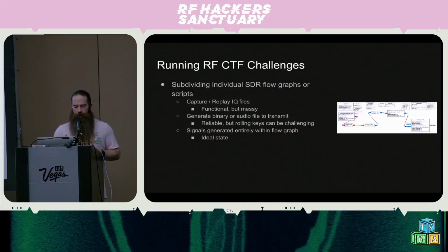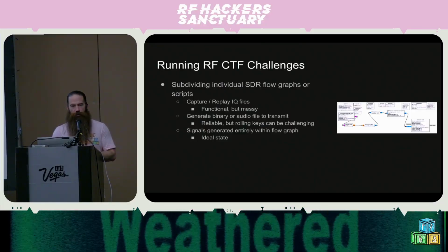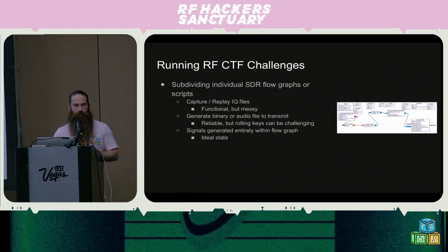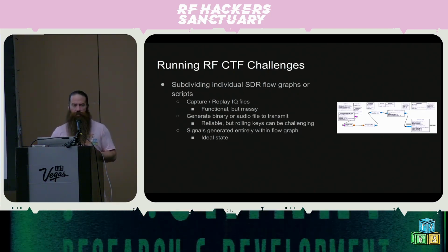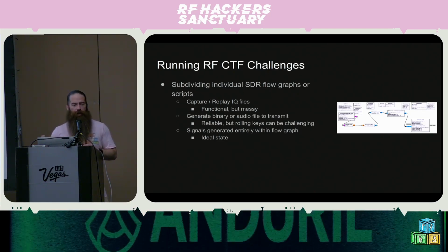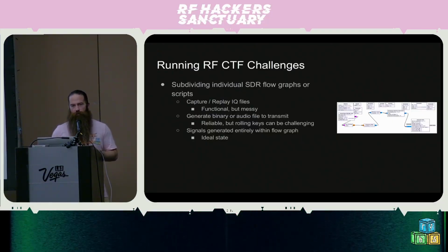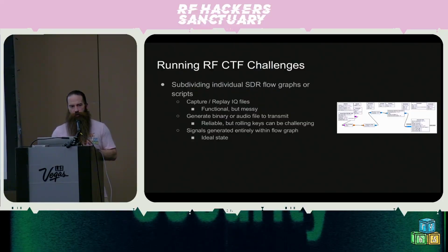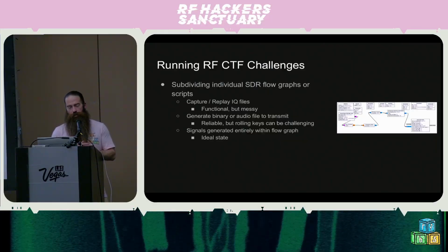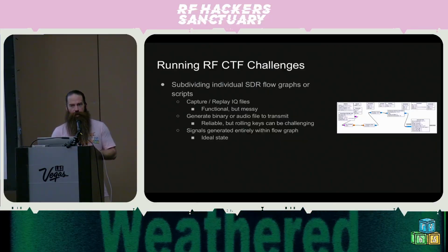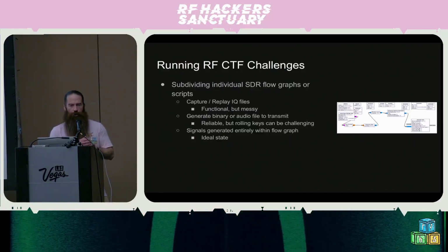Next way, generating binary or audio files to transmit. This is how some of our challenges are done right now, where you generate a binary file and then use that in a more generic script to transmit that out of your SDR. So that's reliable, but rolling keys can be challenging. Right now, with the challenges that we have running out of the SDR box, it takes roughly 2 hours to roll the keys. Not because there's that many challenges, it's just that the time it takes. FLDigi is what we're using to generate some of those keys, and it's doing everything in real time. It's meant for interactive use, and so it is replaying everything or encoding things in real time.